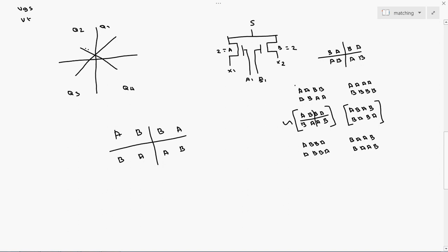This is a mirror image. These two B's, the on and off time in between them covers an equal area. The same for this A and this A, from this A to this A on and off it is the same area. From this B to this B, the distance between them is the same area. All the A and B transistors lie in the same area. So here we have somehow reduced the errors introduced by the process variation.